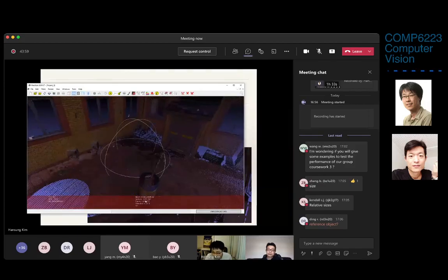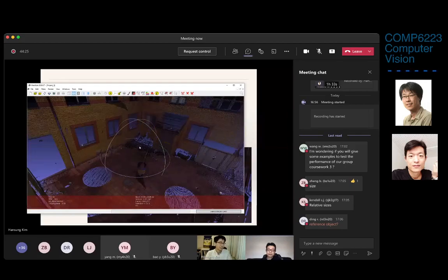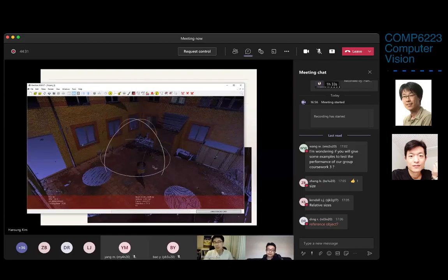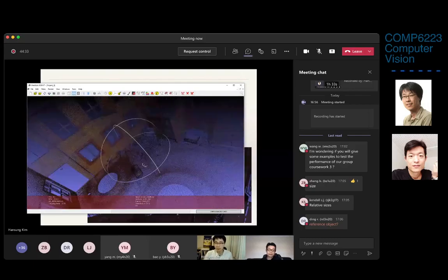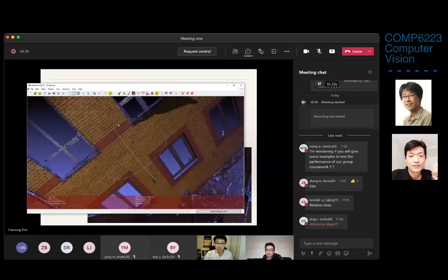At the moment, it has 1.7 million points, but this one is extremely downsampled. In the original scan, from only one scan, I got around 50 million points. It's very, very dense. The problem is that I could not really load it onto my PC because of memory problems. So I downsampled it extremely, like 10 times or something like that. I also did some other post-processing and made this point cloud. You can see the individual points right here. And you can also generate some mesh from that.